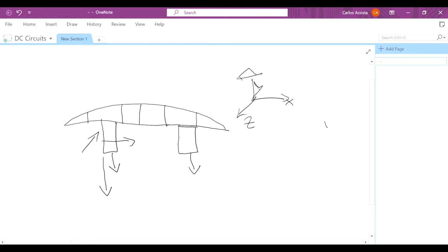They need to find the shear load, which is what happens when there's wind in different directions. Is the bridge going to be able to sustain it? Is the material strong enough when there's a traffic jam? So things like that. You want to know the maximum load, the operating load, the frequencies of the load. If this starts to oscillate because of cars going at a certain speed, this is going to have a frequency that you want to make sure is different from the natural frequency of the bridge. Otherwise, they can start oscillating pretty dangerously.